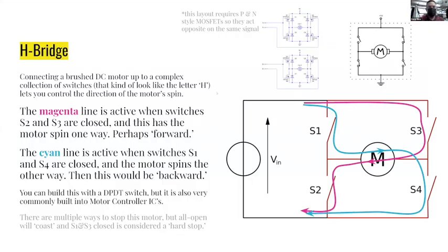So how do you control a motor? We talked a lot about motors. Servos are the easiest. They have their own built-in motor controllers, but everybody else is going to need to have something. Most of the time when you have a motor, you want it to be able to spin in 2 directions. The simplest is the circuit with a transistor, but the H bridge is the classic iconic way to drive a motor so you can get 2-direction motion out of it.